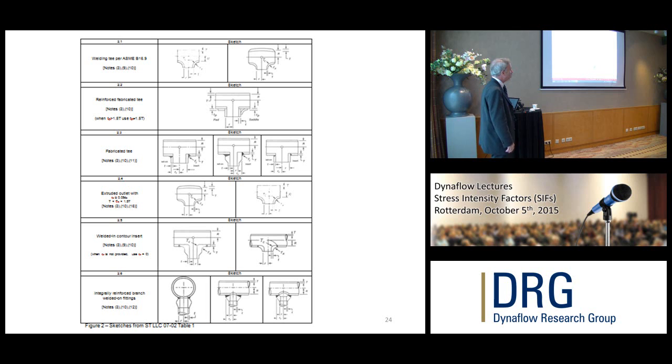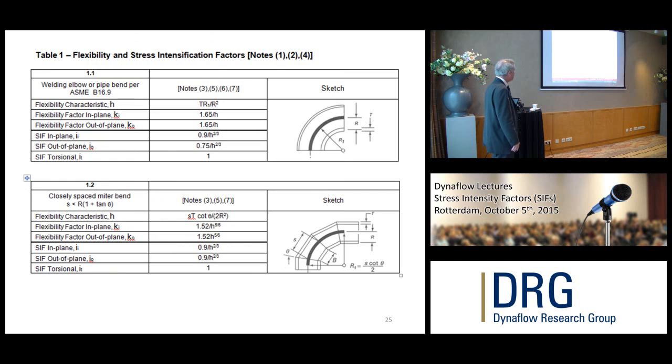There's 2 different shapes for contoured welded in set-in fittings. So all of these are valid, and everything is referenced by a number, just like the European code does. So you don't have to call out these obscure names, you call out sketch 2.6. So 2.6 is an OLET, so everybody knows that now. So you don't have to guess at names. Weldolet is a trademark name of Bonney Forge. So if Bonney Forge gets mean and they can stop you from using that name, well, sketch 2.6, nobody can stop you from using that.